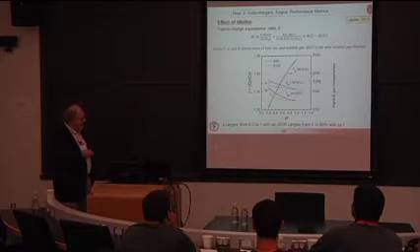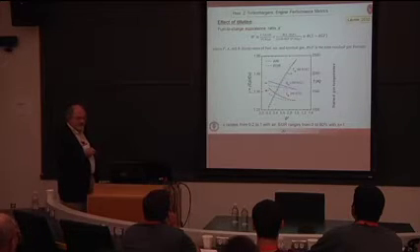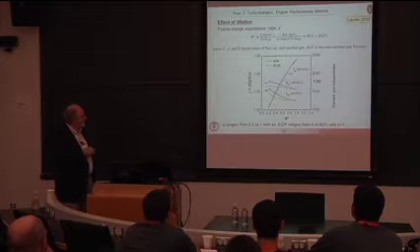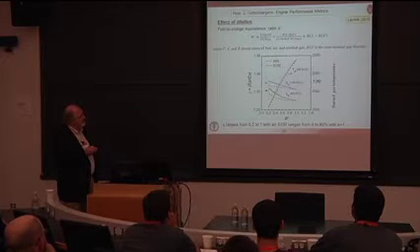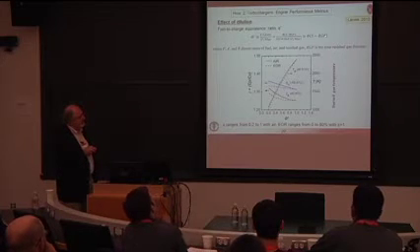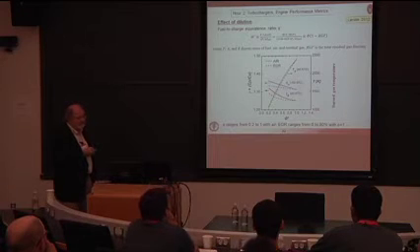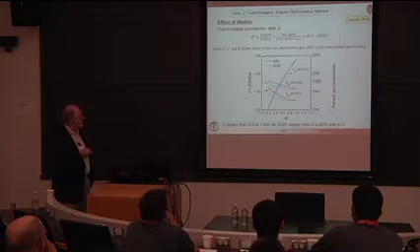So you can either have a low equivalence ratio by having a lot of air and a little fuel, or you can have a lot of recirculated gas products and still have a stoichiometric mixture for the amount of oxygen that's in the chamber.